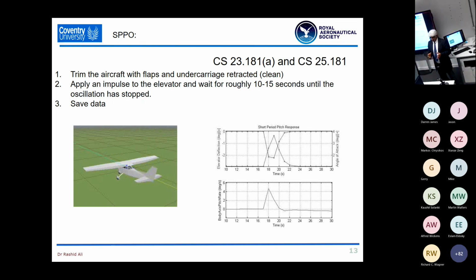So there's a lag. My advice to you is, when you're flying X-Plane and you make an adjustment, just let the aircraft respond before making another adjustment because you think the aircraft's not moved. So you anticipate that computational lag before you apply input.